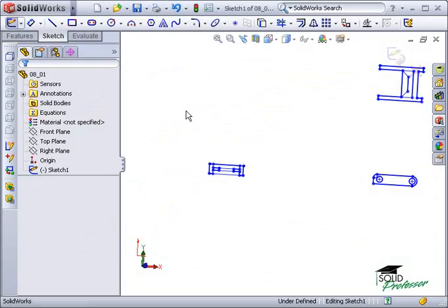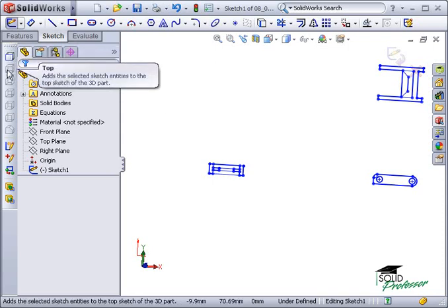When SolidWorks imports your 2D line work, it places it in the 3D SolidWorks environment. To use this line work for our 3D features, we'll need to orient the views into their respective positions, such as front, top, and right, and then make sure they're all aligned with one another. When SolidWorks imports a DXF or DWG file, it also turns on a 2D to 3D toolbar.